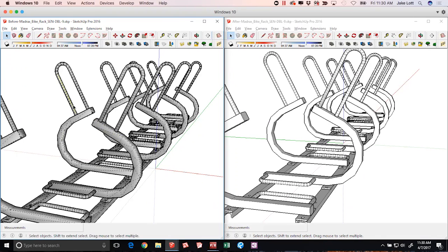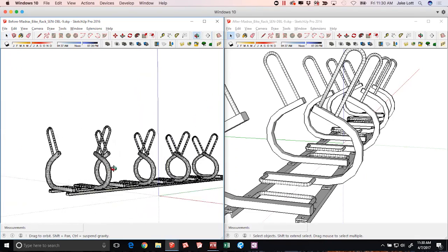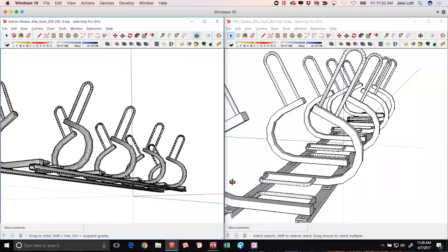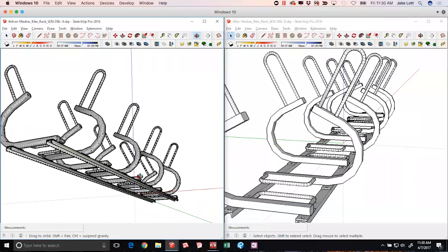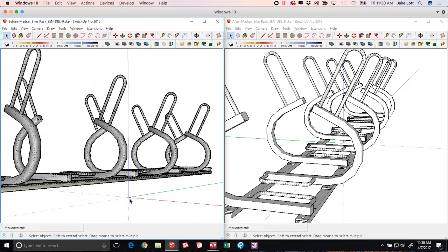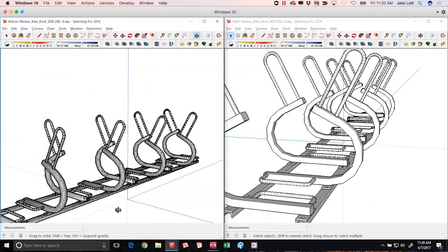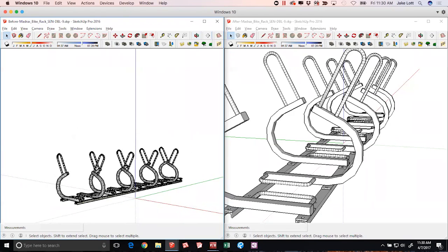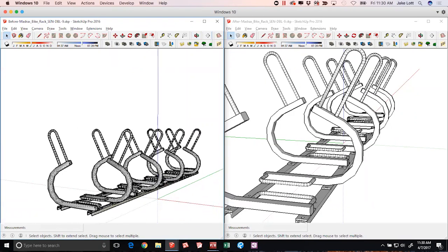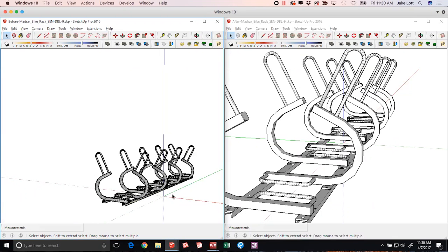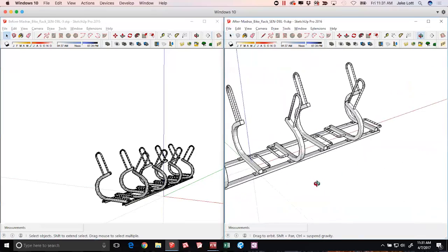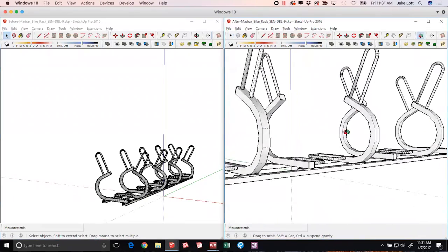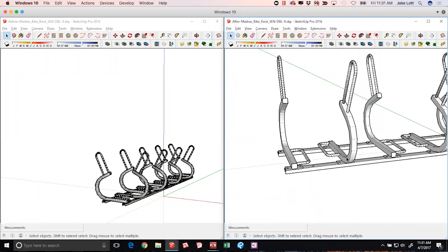I can click on any of these. These aren't grouped at all. And this isn't something that we've mocked up or created to show drastic measures here, but the actual insertion point, the axis of this guy, isn't even sitting on the point. These items are built for reference, and you can put it into your model. But what's not considered all the time is how it can be linked together like we showed in that first demo. So we need to make sure that ours is at the proper insertion point at 0, 0, and that has that proper setup.